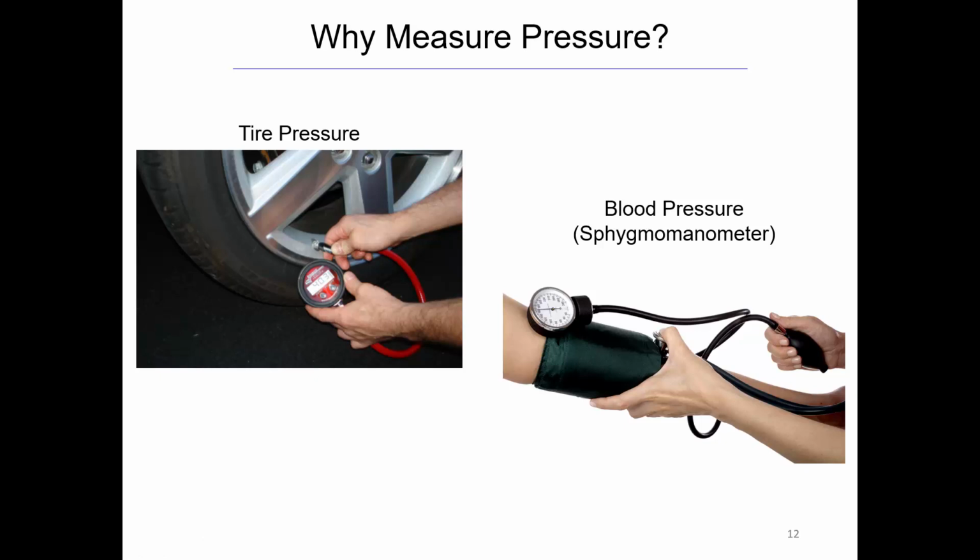There are some other methods that measure how fast your wheels are spinning. There's usually a metal tooth on a gear type of thing that passes by a magnet wrapped in a wire. And when that metal passes through that magnetic field, a pulse is generated. So the rate that the tire is spinning, that RPM, is measured through that device.